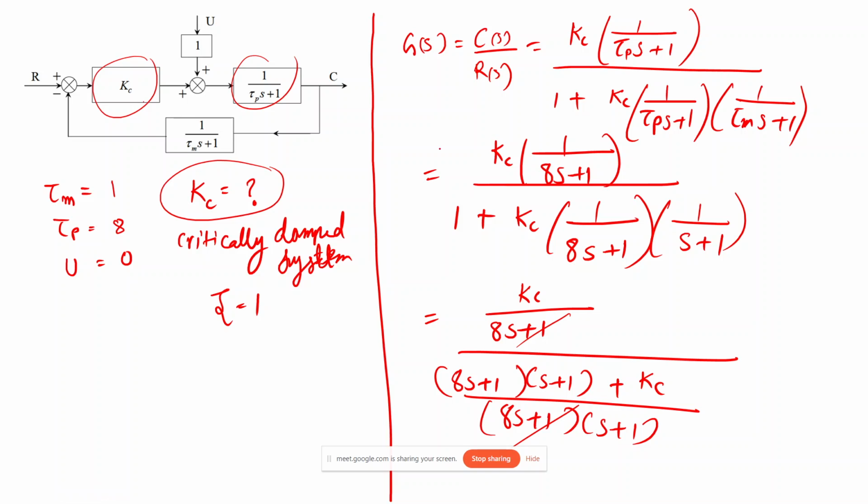So in this, we simplified this block diagram to find the closed loop transfer function relating the output C and the input set point R, C by R. So we usually write this transfer function, the numerator will be the multiplication of these two blocks, and the denominator will be the multiplication in the feedback loop. So basically this is our feedback loop.